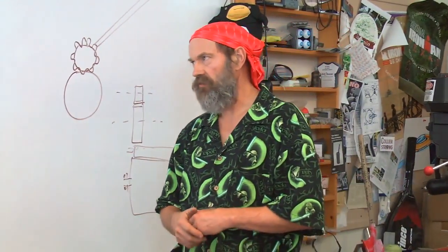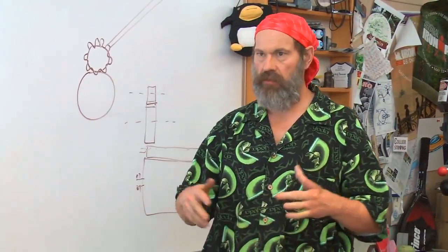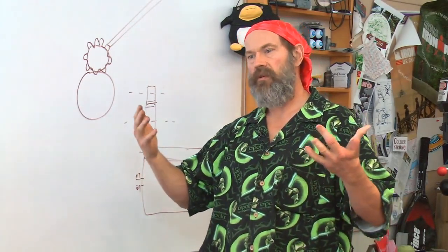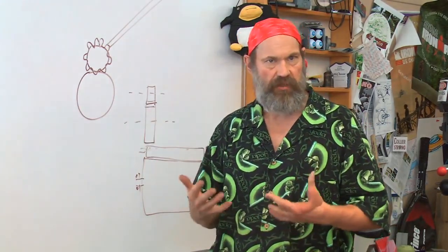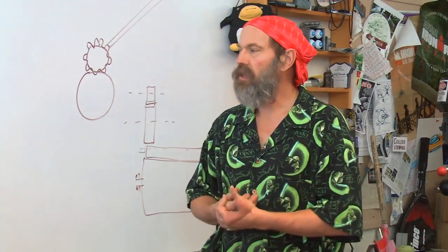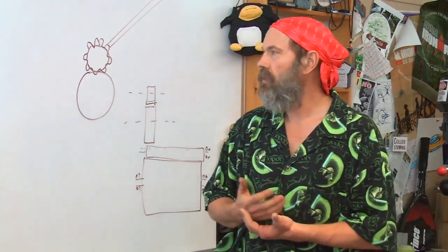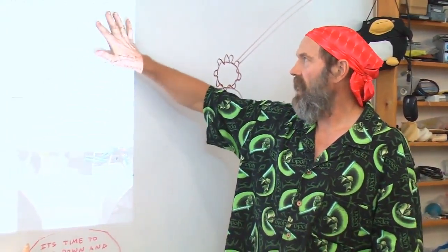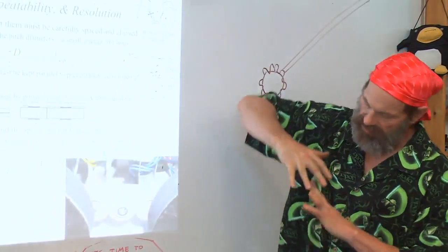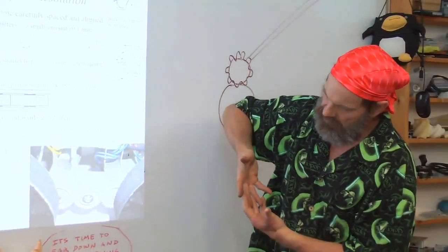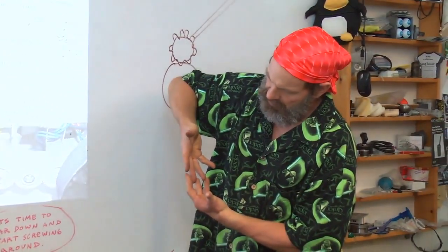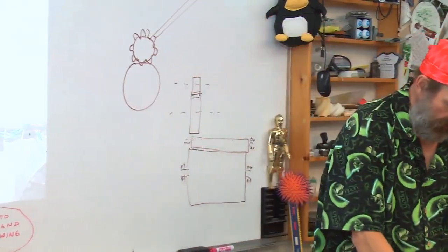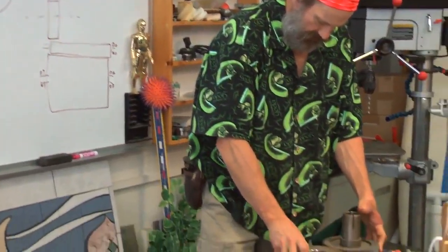Okay, you design your gear train. It handles the loads you want, but you want to have a high precision mechanism that will perform with minimal backlash. And remember we talked about in the screws the idea of preloading. How do you preload gears? Lots of people have worked on this over the years, and you have to have what's called backlash in the gears. You can't design gears and just push them together radially to force them to engage. You can't arbitrarily, here I'll show you here.